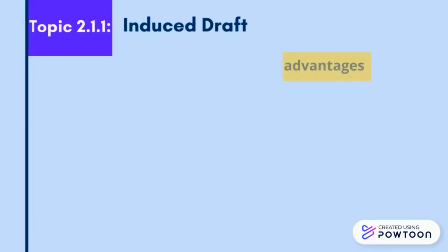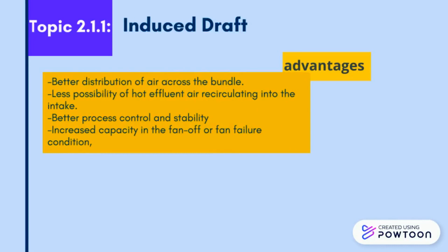The advantages of induced draft: 1. Better distribution of air across the bundle. Second, less possibility of hot effluent air recirculating into the intake. Third, better process control and stability. Fourth, increased capacity in the fan-off or fan failure condition.